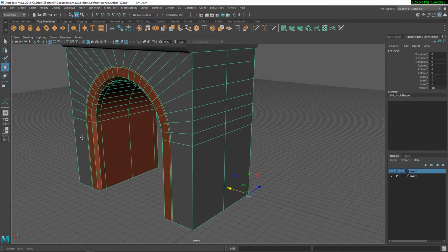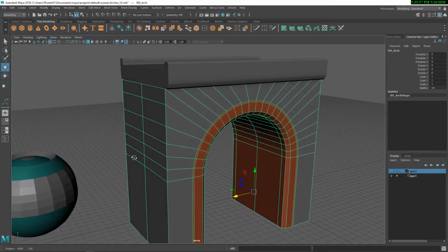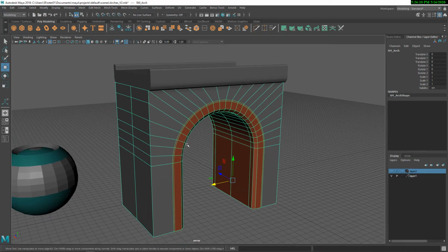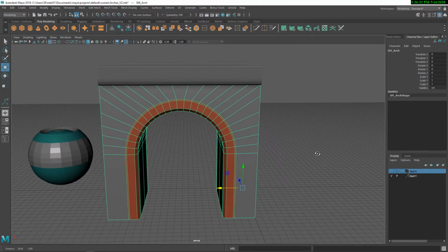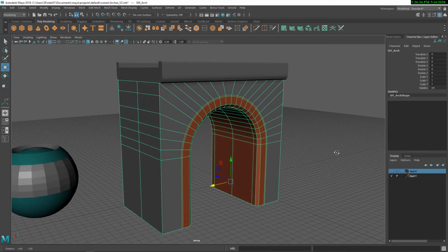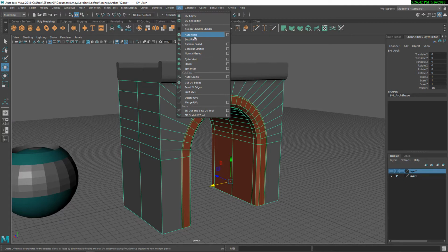The main reason that some people triangulate on very complex hero meshes that have a lot of polygons is that sometimes you want to see the way the polygons triangulate. And why are they triangulated? Well, they're triangulated because the GPU actually works in triangles. You're making it native to the way the GPU would be working. Much of modeling is often taught in quads, but the GPU actually processes in triangles. In addition, then you can set up your UV coordinates, and you can even have multiple UV sets that will export. In this case, I just put in automatic mapping for example purposes.